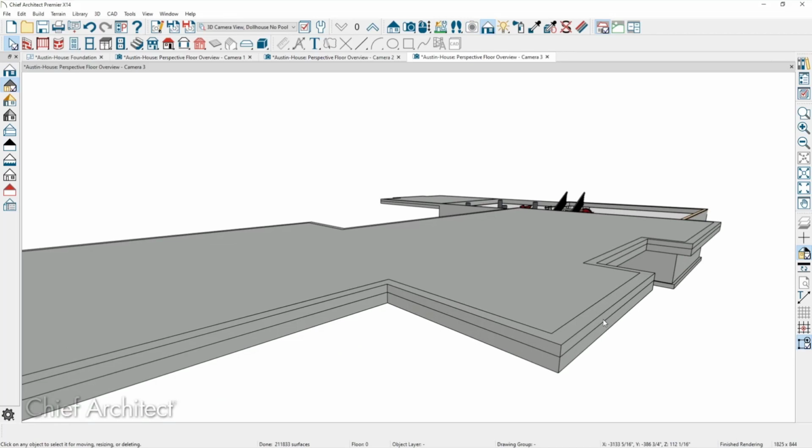Okay. So that's what happens when you try and put a slab footing underneath the slab, it does weird things because it tries to put a stem wall on top of it. Okay. My workaround is I'm using a 3.5 inch stem wall for my thickened slab beams and just showing the footing, even though I know it's not right in 3D graphics. Nobody is ever going to look at it but me. Sure. Yeah. But it's basically an 8 inch thickened slab with 45s at the bottom. Okay. 2 foot wide. Okay.